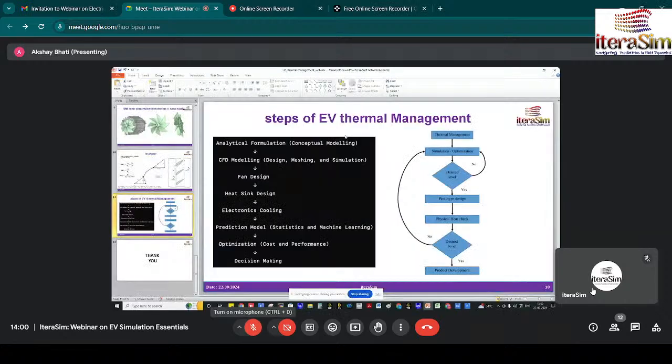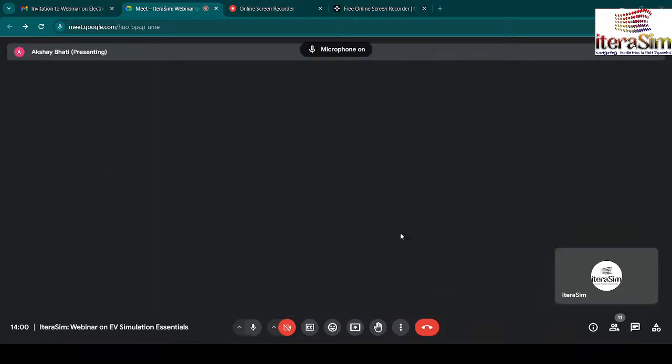But if you want to optimize that fin length, basically you take a rough fin length based on your calculation. After that you do the simulation and check up to what length the fin system gets into equilibrium with the fluid flow. If it gets to equilibrium, there would not be any heat transfer, because both temperatures would be the same, there would be no temperature difference. So it is a simulation part. First you develop your rough design, after that simulate and visualize, and you can optimize what fin length I should take.